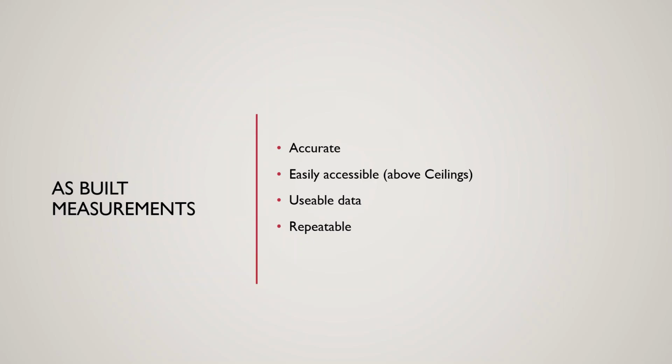If you can get a laser scan done on that first trip, or have somebody go out and take the laser scan for you, then you have a piece of data that's usable for the whole period of the project, and it's usable by more than just yourself.